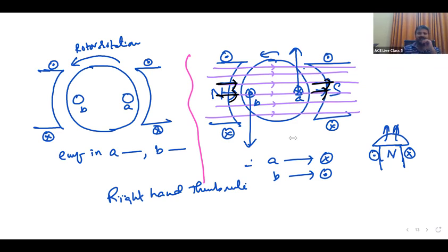And the third case, if both the conductor and the flux are rotating, but there is relative motion. One is 15 RPM, one is 400 RPM, relative motion is there, then flux cutting action takes place. But when both are rotating in the same direction and the conductor is slower, you have to assume opposite. If the conductor is faster, no assumption. Like that. The last case is if both are originally rotating in opposite directions, no assumption is required, since relative motion is already increasing.